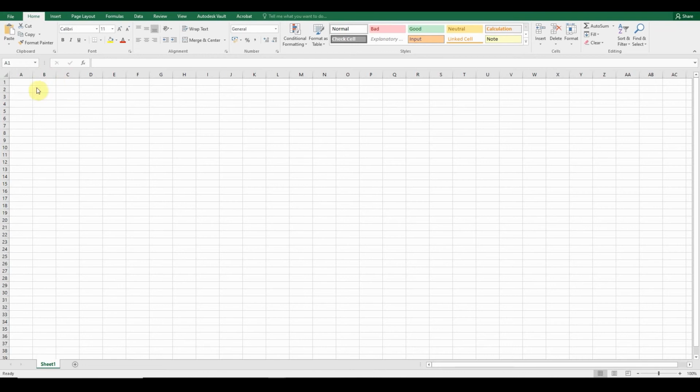Now it's very important that ANSYS reads this code correctly. So in C1 here, what we want to do is give it a code. So that's hashtag NACA 0012. And then on the first one here, it's going to be hashtag group. The second one's going to be hashtag point. Then we're going to give it the X, Y, and Z coordinates.